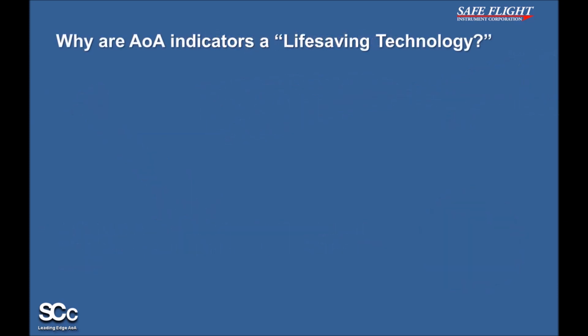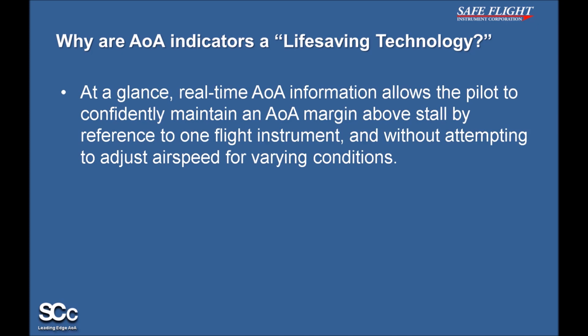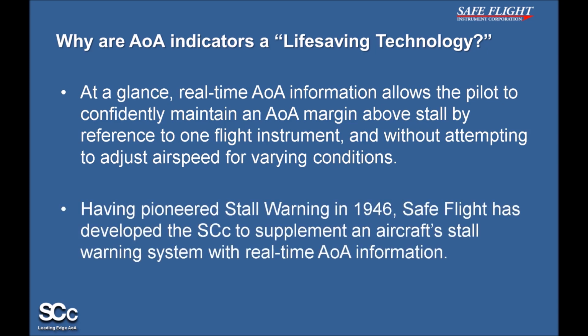This answers the question of why AoA indicators are a life-saving technology. At a glance, real-time angle of attack information allows the pilot to confidently maintain an angle of attack margin above stall by reference to just one flight instrument, and without attempting to adjust airspeed for varying conditions. Having pioneered stall warning in 1946, Safe Flight has developed the SCc to supplement an aircraft stall warning system with real-time angle of attack information.